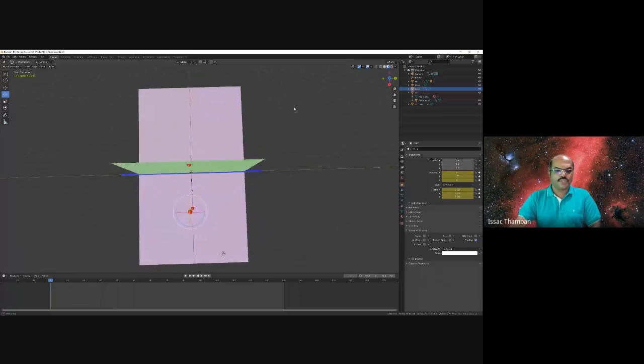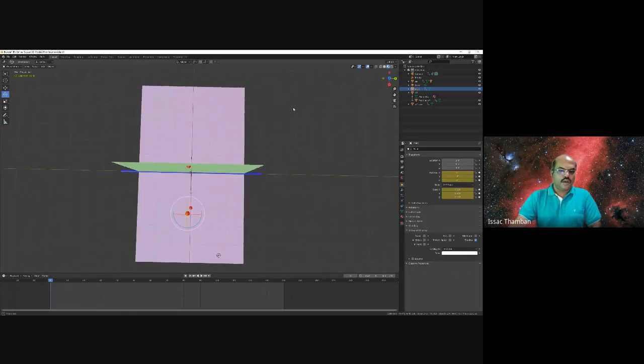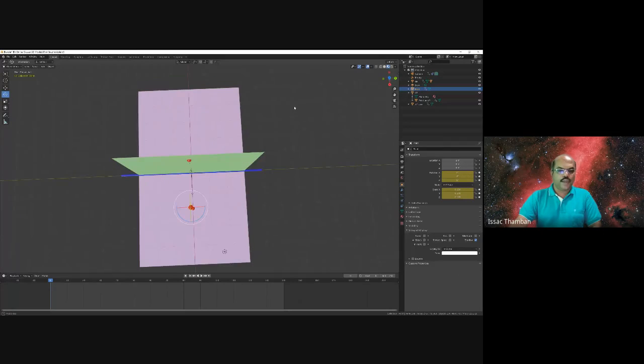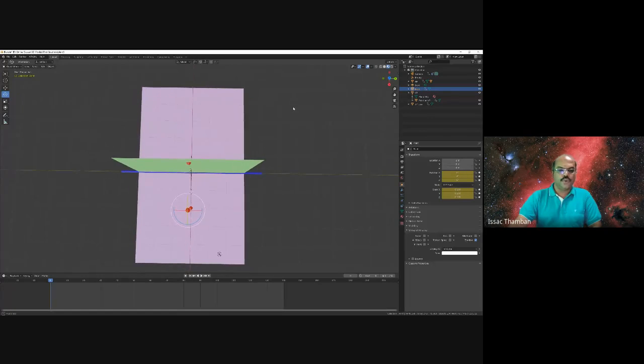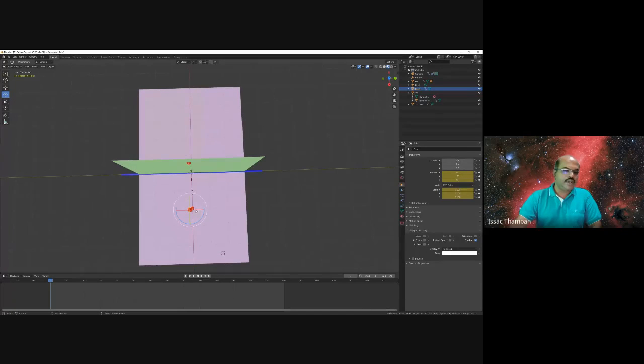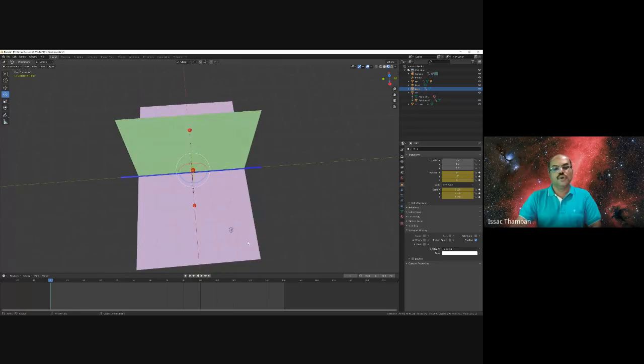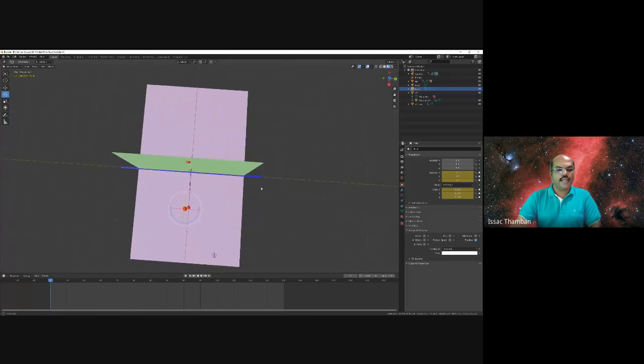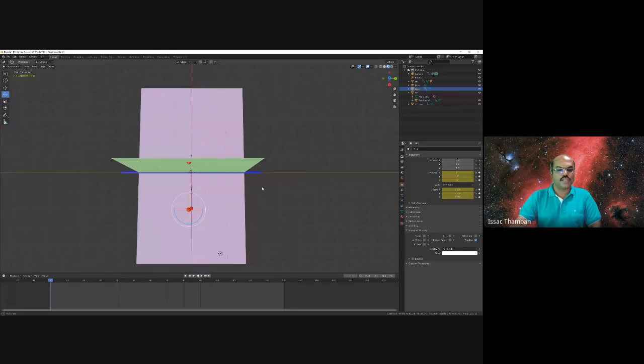And if the observer is positioned at the top, and suppose that he is looking from the top towards the object, then the projection of this object will be obtained over the horizontal plane, and this projection is known as the plan, or it is called the top view.